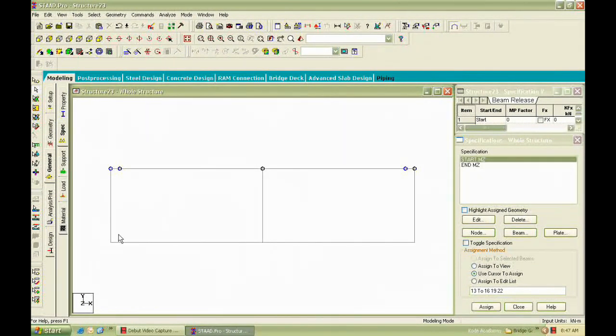I don't want to again select all the, use this. Actually my beam layout is same for all the floors, so I have this advantage of copying only that floor to all others. Now I would have to assign the releases for the ground floor fence beams. I don't want to take that much effort, so I'm deleting them.